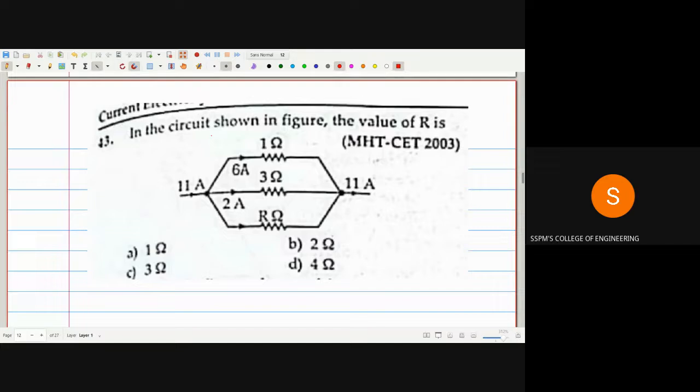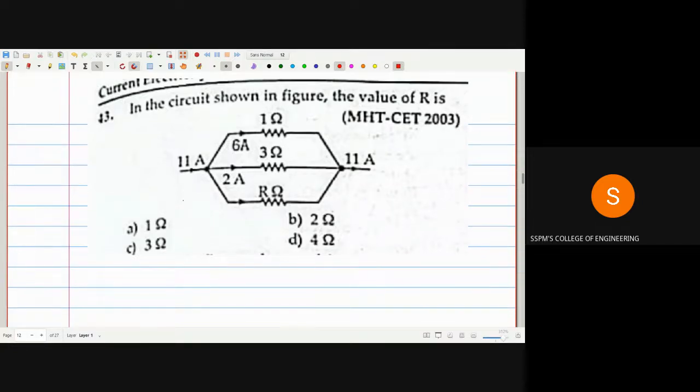इथे बघा, हा एक्झाम्पल पक्षाशाने लक्षात येईल. तुमचा केसीएल किर्चॉफ्स करंट लॉवर डिपेंड आहे. In the circuit shown, find the value of R. R ची value find out करायची. So before finding R, first of all, you have to find how much current is flowing through the third branch. आता third branch कुठे आहे? इथला करंट फाइंड आउट करायचा I. आता हा जंक्शन A घ्यायचा आणि अप्लाय KCL at junction A to determine I.